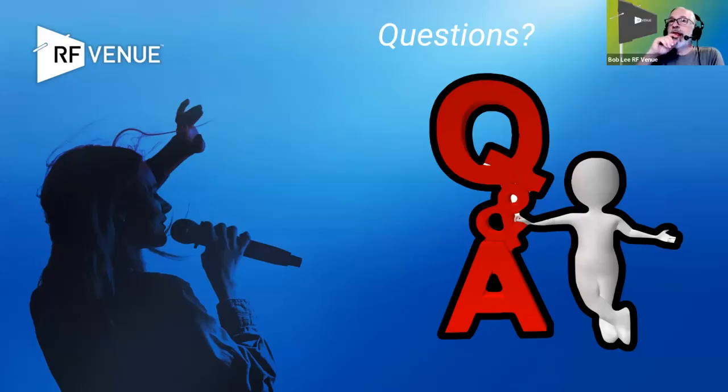I'll add something to that. Sometimes just locating the receivers. If you've got a really difficult situation where it's just a really long distance to the stage or something like that, sometimes it might be better to locate the receivers closer to the antennas, wherever you happen to put them, and run longer audio cables, because good balanced audio lines are fairly low loss compared to RF coax cables.